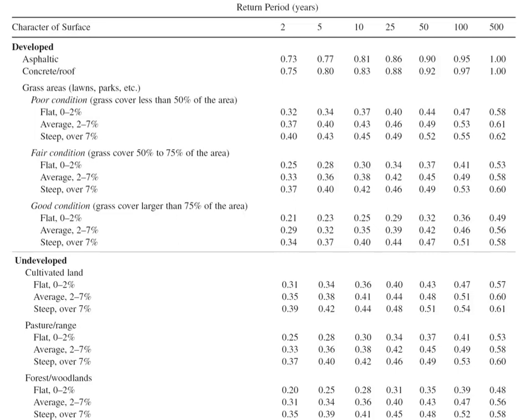Probably raining harder. So later your storm more. Well, it's definitely, yeah. A 25-year storm is a storm that's so intense it only comes around once every 25 years, statistically on average. So it is a more intense storm. You're right about that. So why is it that during the more intense storm, instead of having 73% runoff, you're having 86% of it running off?